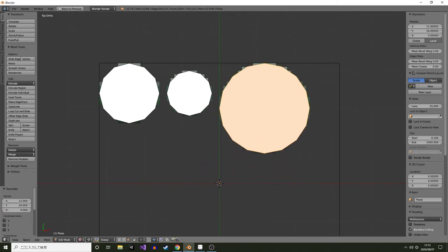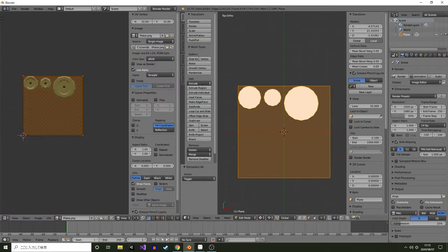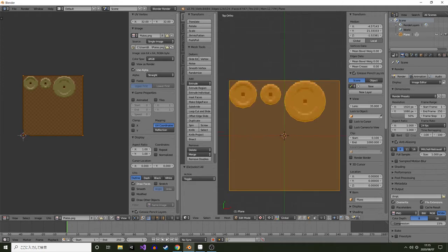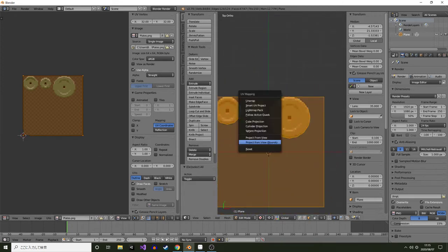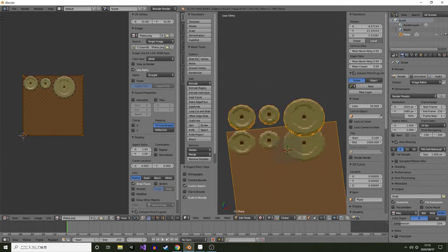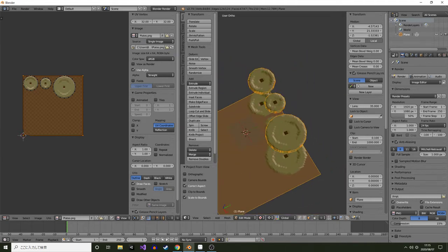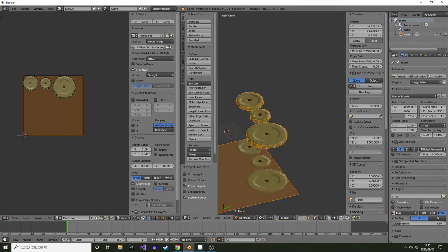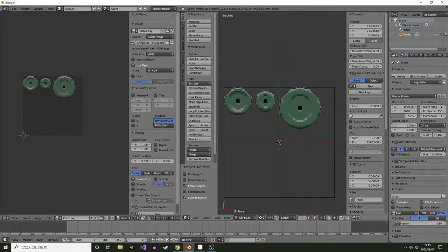And this is where the magic happens. So you select everything, apply the texture, of course. And right now it's just nothing. But if you go unwrap, project from view bounds, it slaps on the texture pixel perfectly, which is nice. But you might be going, hold on, we've got stretched bits over here, and I'll show you what I'm going to do with that next.